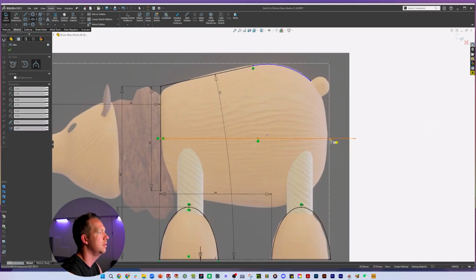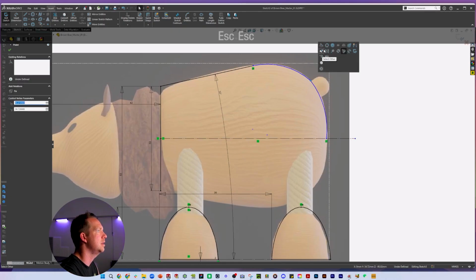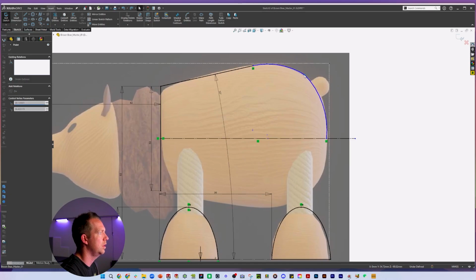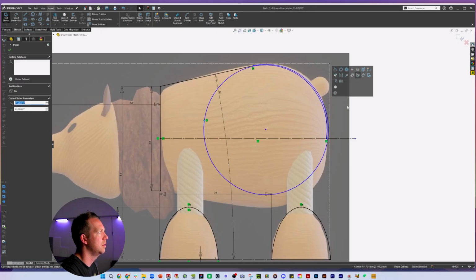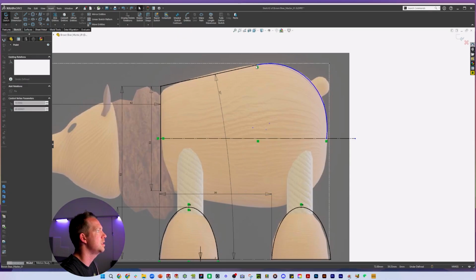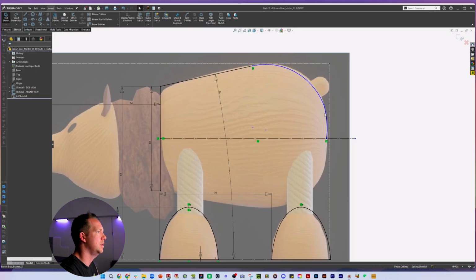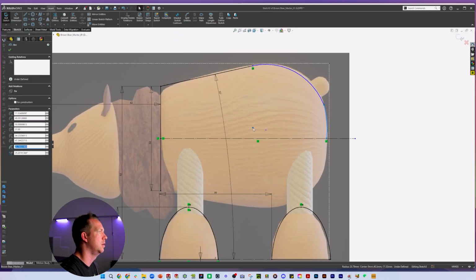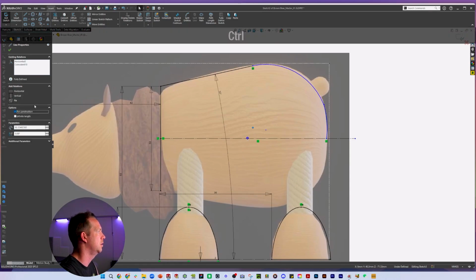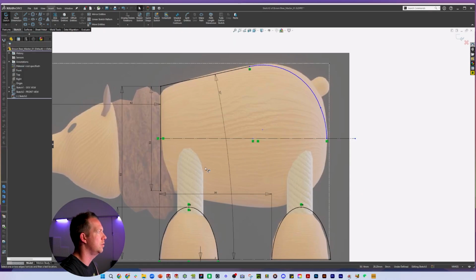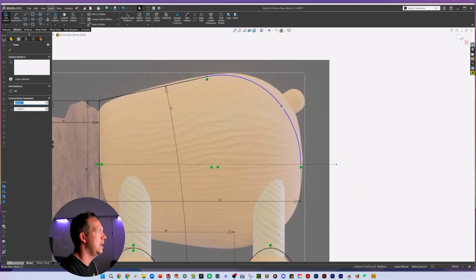Let's start here and have that, make these tangent and do that. Need to bring that one right back, right down, make that point tangent now. Nope, still doesn't want to do it. Bring this edge up, bring this edge down. This one definitely needs the center point to be on the construction line through the middle. And I also want to dimension the length. We can do a 3rd radius, but these two might find a nice happy spot now.